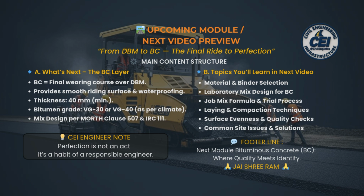Minimum thickness 40 mm. Bitumen grade VG 30 or VG 40. Mix design as per MoRTH 507 and IRC 111. CEI Engineer Note: Perfection isn't an act, it's the habit of a responsible engineer.